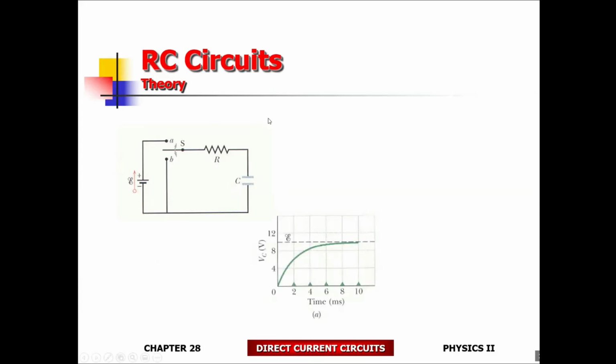You can control it two ways. Number one, the capacitance is going to give you how much charge you can place within the capacitor. Resistance is the stuff that you need to use in order to control the charge up as well as the discharge time. So here's your battery, and here's your switch. You can turn the switch on, which means that it's going to charge up, or you can turn off the switch, which means that you can discharge it.